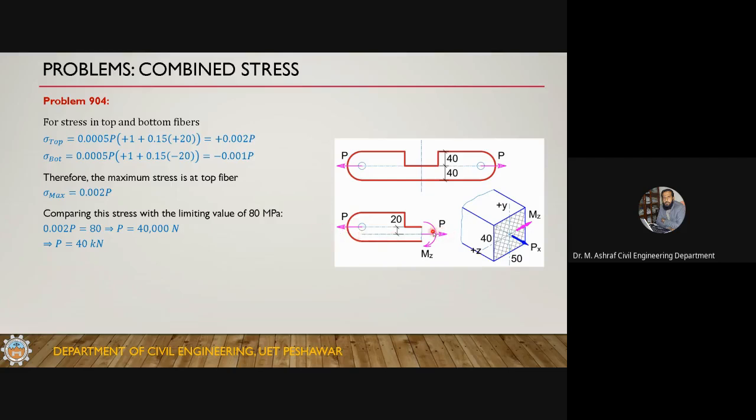So if you just pull this up, what will happen? It will move like this, it will bend like this. Since the forces cannot transfer like this, the force will transfer like this. This is the stress path. Here it will pass like this, then coming here and then here, and it will pass like this. So this portion is under bending also, and this bending is due to this eccentricity.